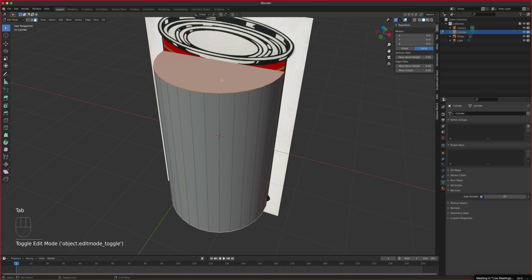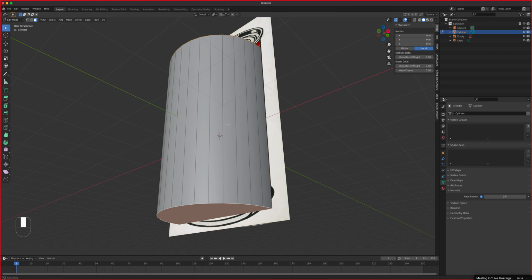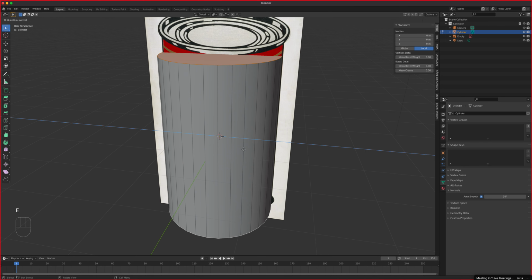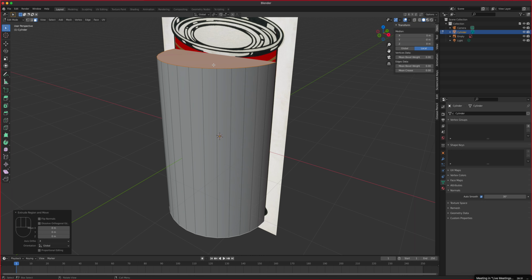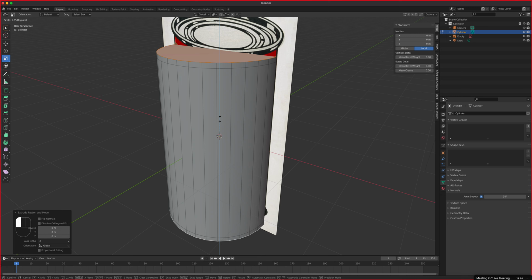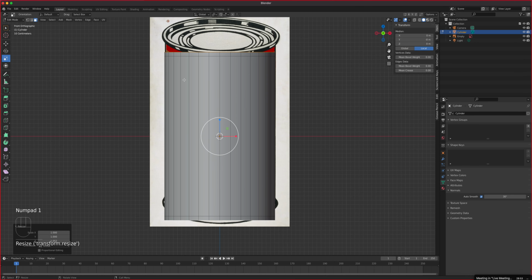All right, so I'm going to select the top and the bottom at the same time. I don't know if you guys remember the boombox. What we did here is press extrude, and then right click to cancel. So I didn't really extrude it by moving it, but there's extrusion in there. There's actually two tops and two bottoms at this point. In order for those to move in both directions, we can't use the move tool because then they'll move like so. If we use the scale tool along the z-axis, I'm going to scale it a bit. If I go to the top, that's the top lid and then the bottom lid. Okay, maybe a little bit more.